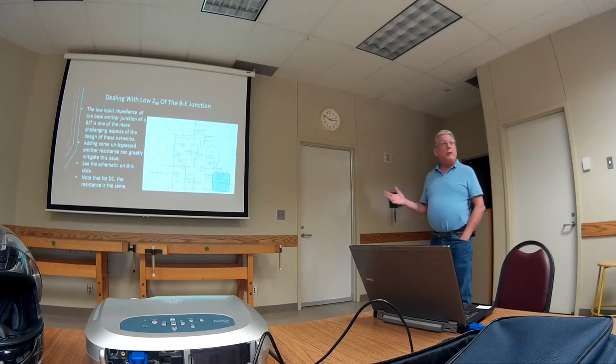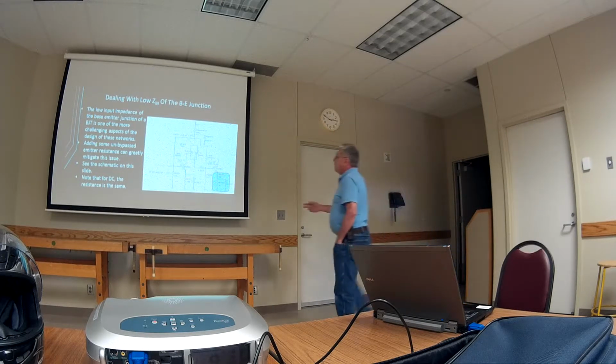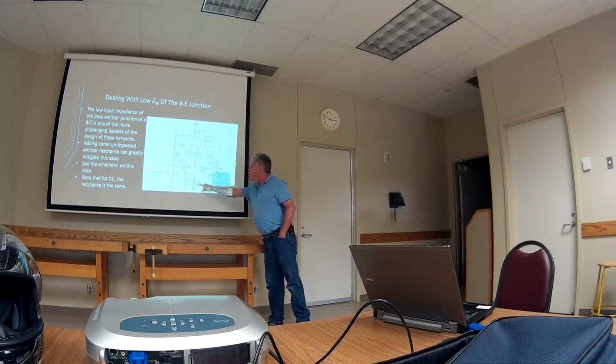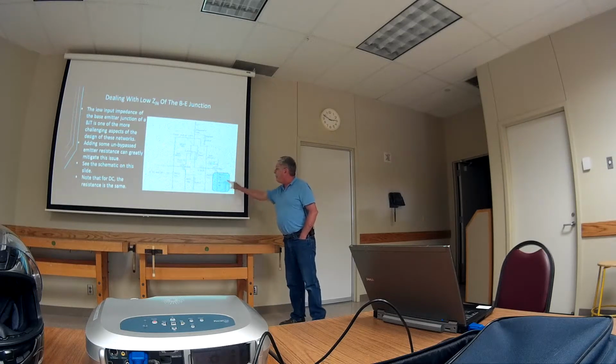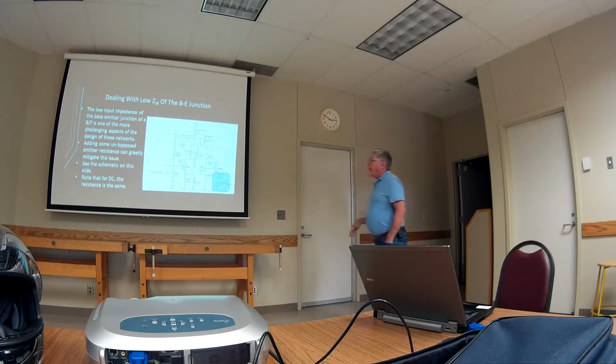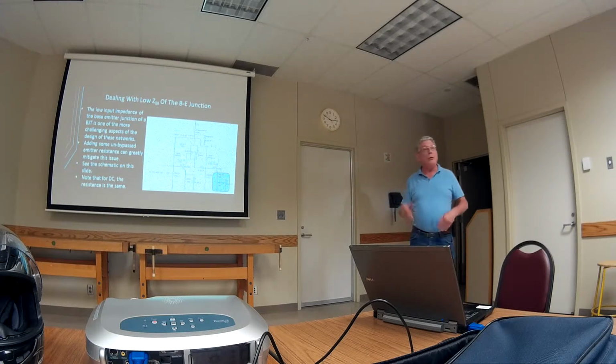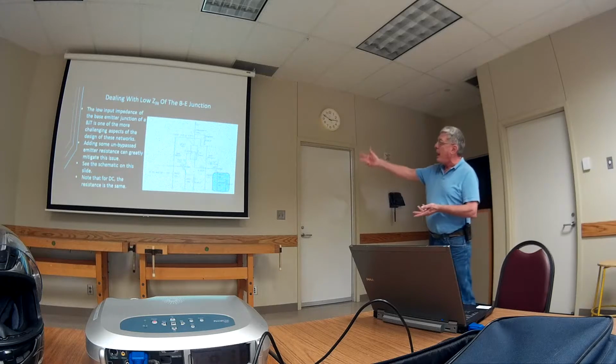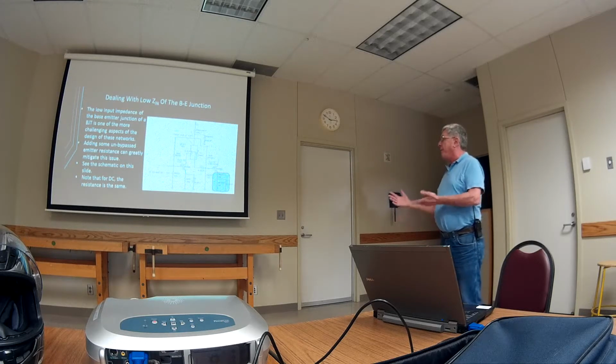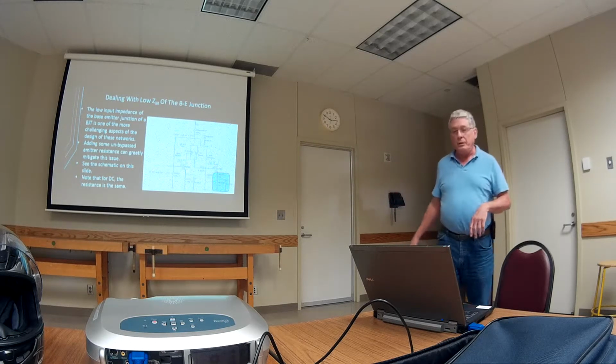Now, you're going to lose a little gain because if you have a fully bypassed resistor, you get the highest gain. Here, we haven't bypassed it all. But, again, everything's compromised. So I've done this many times, and you can juggle those values. It doesn't have to be half. It might be 75 ohms and 25 ohms.